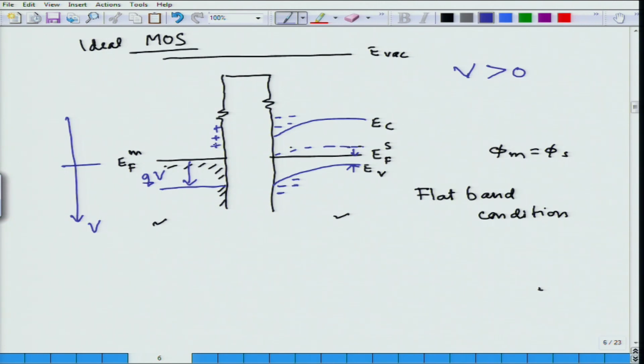And this situation in which a p type semiconductor is getting an opposite type of carrier is known as the depletion region, the depletion of the semiconductor. And what is happening here is, now if I measure the capacitance of this capacitor, it will be the capacitance due to the dielectric and the capacitance due to the depletion region which has been created in the semiconductor.